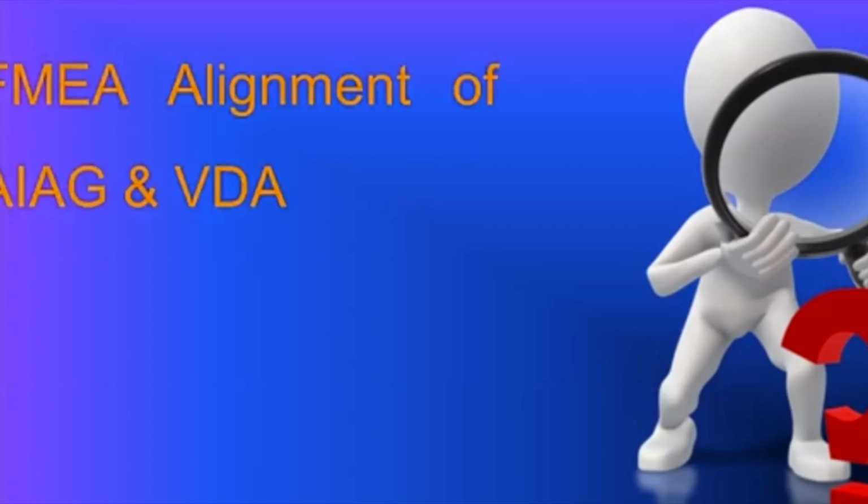Now then, what created the need to revise the FMEA manual? It was done to benefit the multinational OEMs and suppliers by harmonizing both the AIAG and VDA FMEA manual. The suppliers supplying their products to both the European and American OEMs were required to assess their products' failure mode and failure effects differently based on the difference between the severity, occurrence and detection rating tables in AIAG and VDA FMEA manual. This caused confusion and added complexity to the product development and product improvement activities of the suppliers.